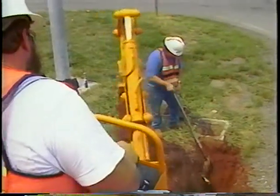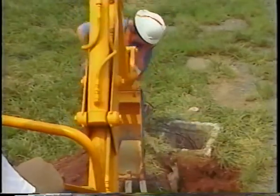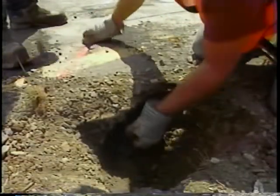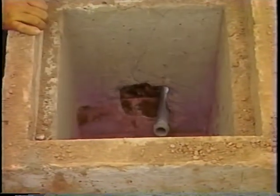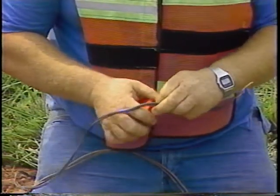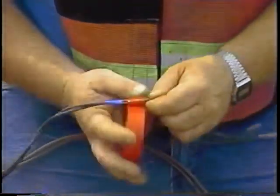The conduit, usually a 1-inch conduit carrying 1 or 2 twisted wires, is connected to the pull box during its installation. At the roadway end, the conduit should be terminated 2 inches below the pavement surface. To protect the wires, attach a non-metallic bushing and tape the wires for several inches on each side of the bushing. And remember, it is important to tag each wire identifying loop number and the start or finish of that loop. In our example, we are using colored tape for tagging.